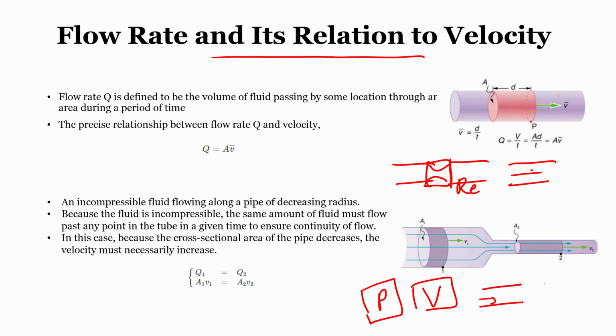Now, this is one such channel. Assume a vessel having a cross section area A and a given diameter d, with velocity v. Now, how are these related? Volumetric flow Q is equal to the cross section area times the average velocity. V here is the average velocity, because the velocity V dash is equal to the distance divided by time. So, on average, the velocity over a given area will give the volumetric flow.